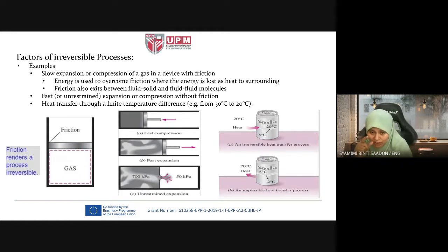For example, the soda here: it is an irreversible heat transfer process, because the change in temperature of the soda is what we call finite, a bit large. Infinite, we cannot really define it. So it is an irreversible heat transfer process. If it's only a very, very slight change in temperature, then maybe we can consider it a reversible process.